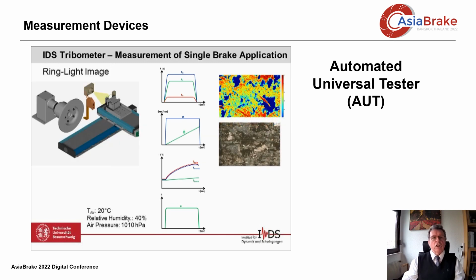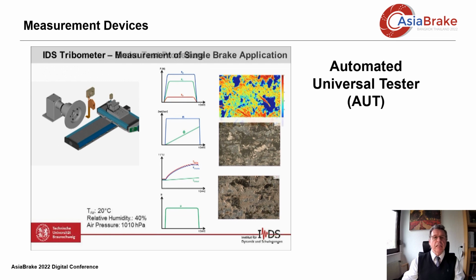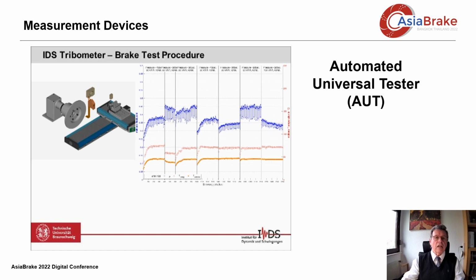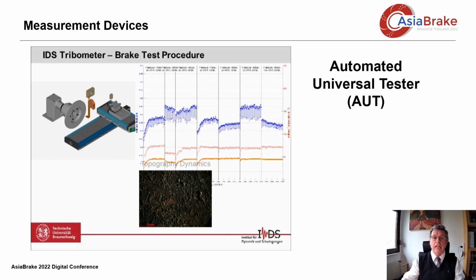The device measures, among other things, the forces, the speeds, the temperatures at disc and lining, and calculates immediately the friction value at approximately 10 kHz. In addition, of course, weather data, noise, and vibrations are detected. We actively use data science techniques for compression and evaluation. We can run fully automated, complex brake applications. We can compress the surface scans to movies.